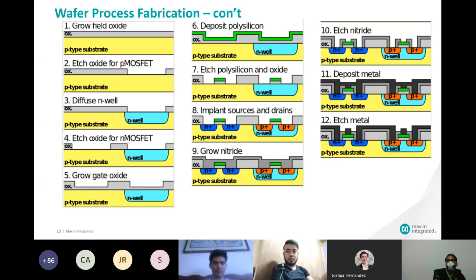But Intel was able to use 3D transistors now, which is beyond the scope of our discussion. For 3D transistors, they're going back to metal gate. But for a typical CMOS process, planar process, not 3D process, we don't use metal gate anymore because the yields are horrible for those metal gate transistors. So we use polysilicon. And then we want to etch out the polysilicon because we just want to put it on the gate for your NMOS and PMOS.